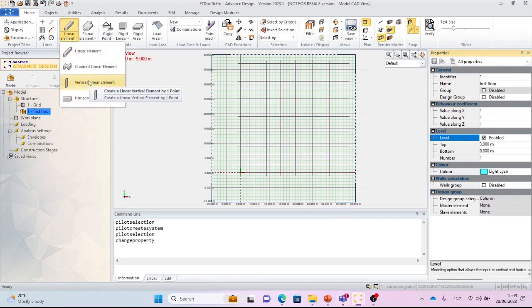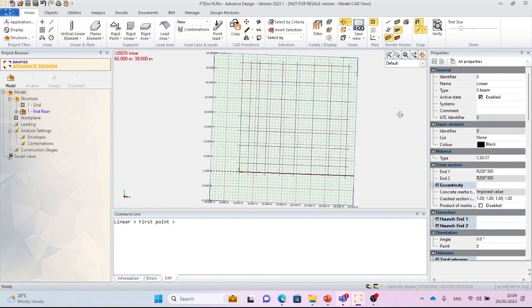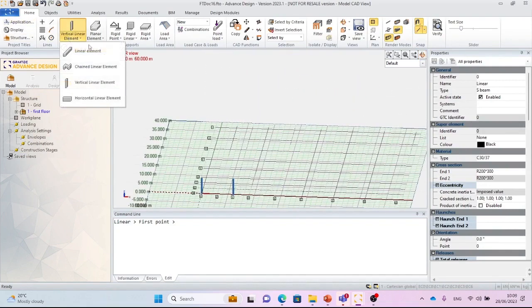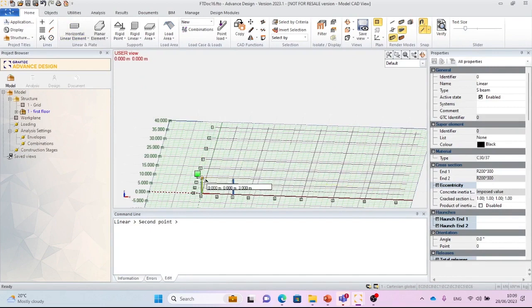By enabling the levels, it's much easier to create the different structure elements, since you can just literally snap the different elements on the grid instead of needing 2 points to create the columns.